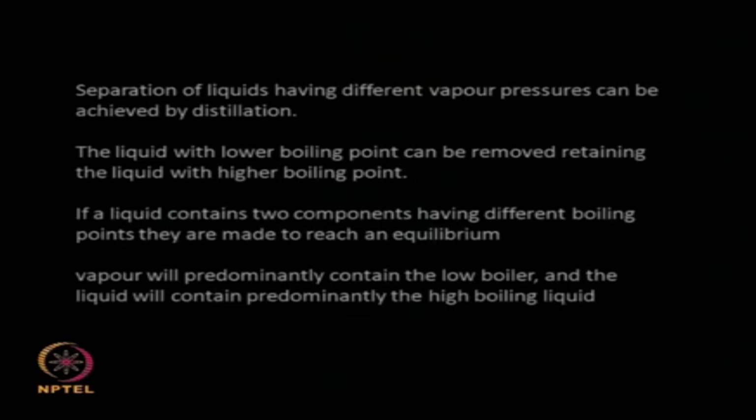When I heat a mixture of liquid, the liquid with lower boiling point goes into the vapor, whereas the liquid with higher boiling point remains in the solution. By doing this, I am creating an equilibrium between the vapor phase and the liquid phase. So the vapor will predominantly contain the low boiling component and the liquid will predominantly contain the high boiling component.